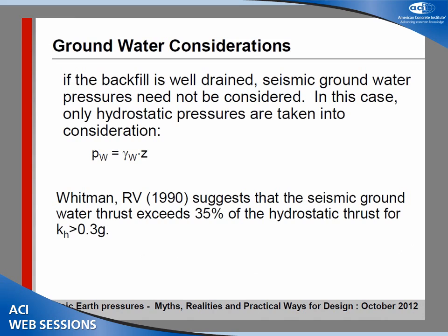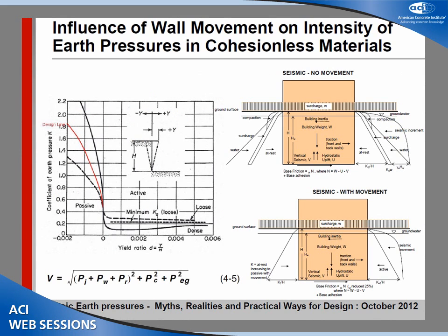Okay, if you had water also in your backfill, then you have to consider that as one of the driving forces. But if your backfill is well drained, then really it's just the hydrostatic pressure which will be acting all around the structure, so it won't really produce any driving forces. But if the backfill is not well drained, then Whitman said that sometimes due to the shaking of the ground, the water pressures could increase up to 35% from the hydrostatic.